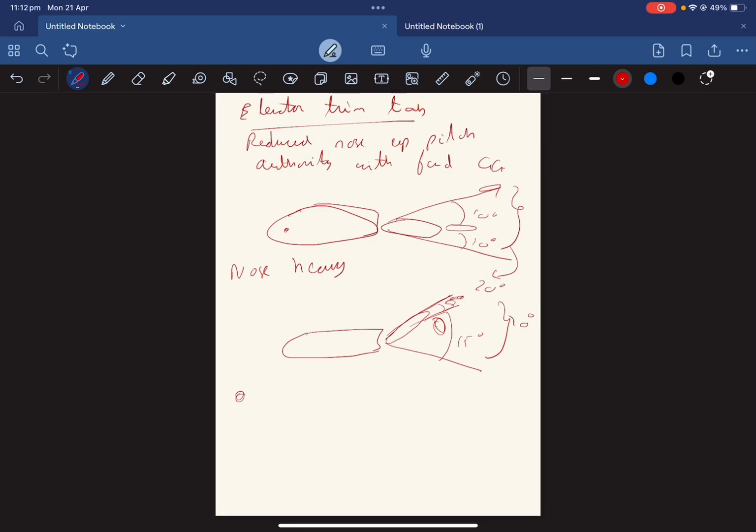Have you guys seen when an airliner lands? Let's say this is the runway. It does not come straight in and land with its wheels flat, right? It lands like this. The main wheel touches and the nose wheel is up. This is called flaring. This is how you protect your nose wheel. If you want to flare your aircraft, you need to pitch up. But since your authority has been reduced, it's going to be hard for you to flare your aircraft. I hope that makes sense.